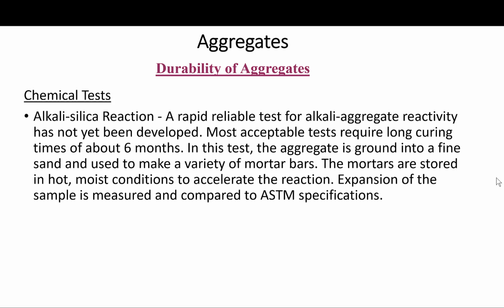In this test, the aggregate is ground to a fine sand and used to make a variety of mortar bars. The mortar bars are stored in hot, moist conditions to accelerate the reaction. Expansion of the sample is measured and compared to ASTM specifications. Again, it's not the best, but those are the available tests.